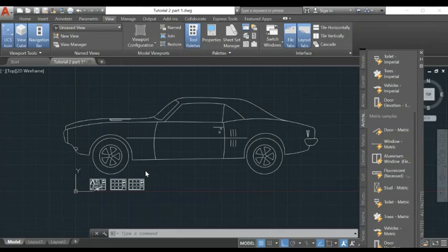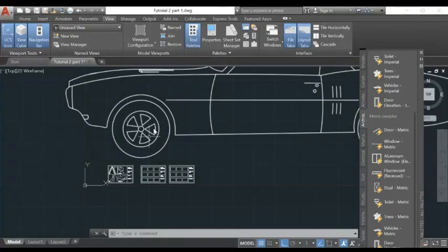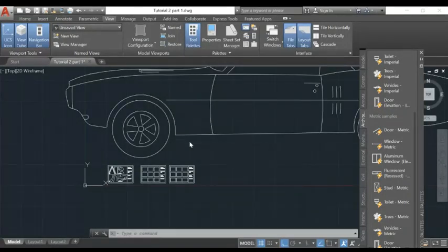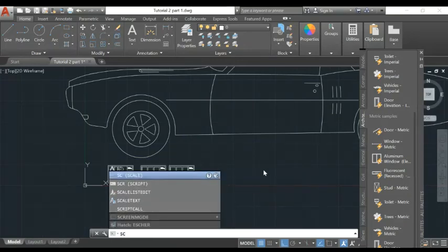All right. So if you measure the proper measurement in metric just now, between the paper and the car, we will show you its actual size object. To be able to put the car inside the paper, we need to scale this. So just go to home, choose scale, or you can just type SC for scale. Short form, the shortcut is SC.